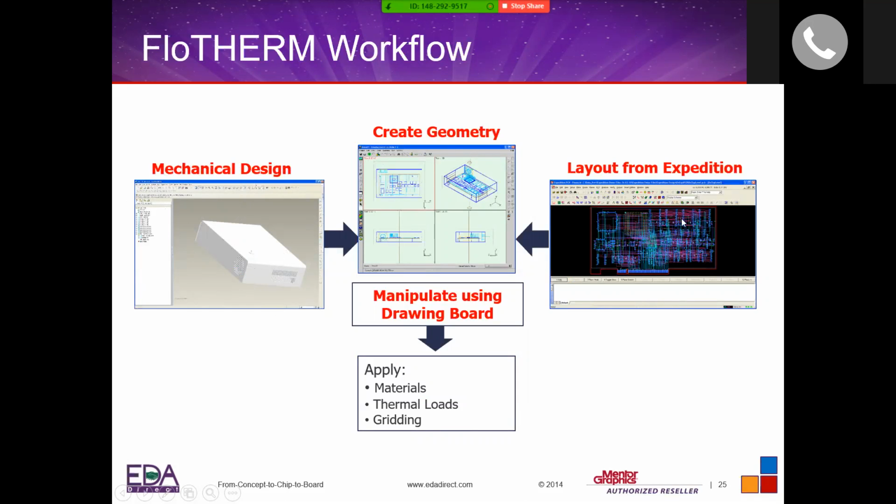And on the other side, you will bring in your PCB board. Okay. If you are using Mentor Graphics layout tools, we can actually export out the thermally friendly file that can be brought in for thermal analysis. If you use other tools out there, Cadence, Allegro, other PCB, we can bring in ODB++, we can bring in IDF board, so files. So we can bring in those EDA files, bring in those mechanical files, and then the